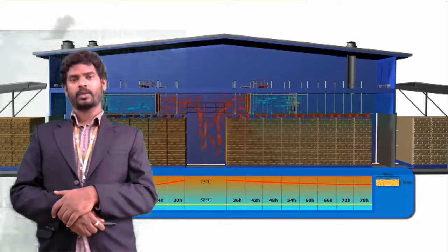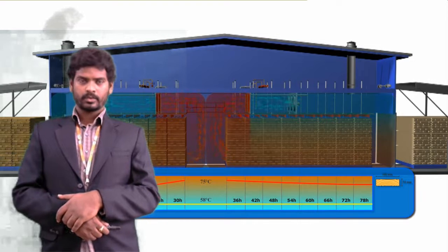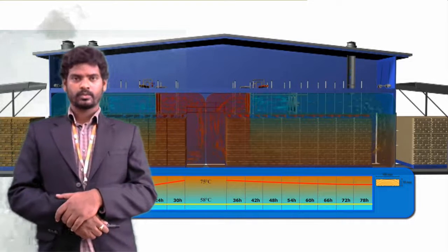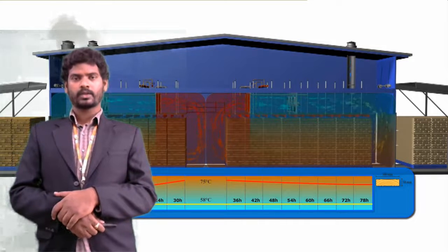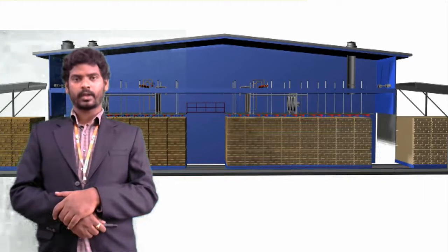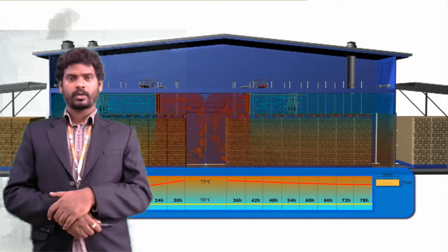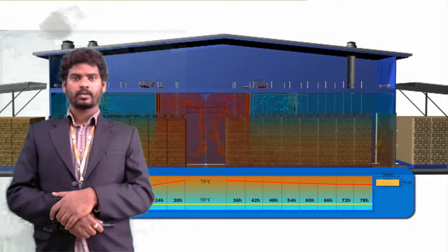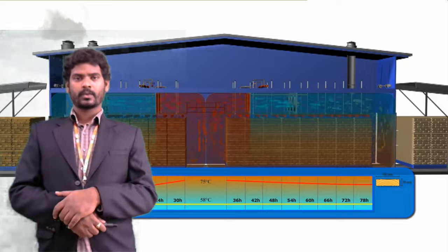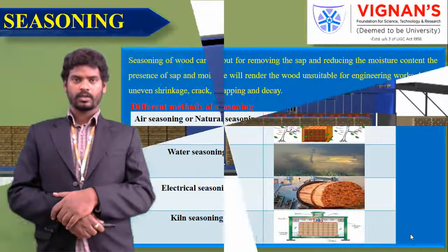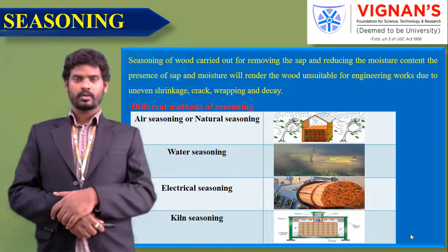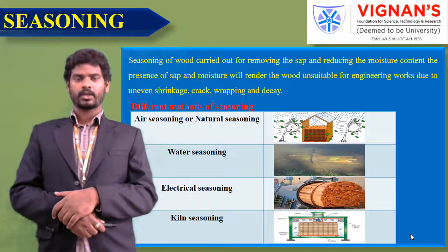The drying of the timber at a uniform rate is maintained by circulating hot air by fans, and a certain amount of steam is added in order to retain correct humidity. The ventilation is provided to avoid overheating and excessive humidity. The timber inside the chamber on a trolley is kept under controlled conditions for about a fortnight, depending upon the initial water contents and required moisture levels.